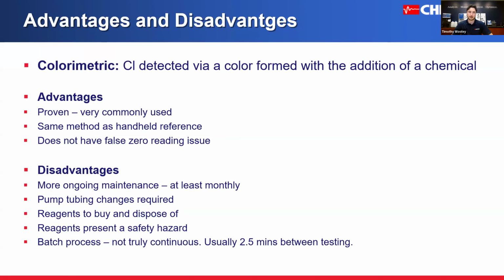And these typically do not have the false zero reading issue. So these are better fit for dechlorination applications or times where there might not always be chlorine in the water. A few disadvantages, we would say, of this type of technology is that they do have more maintenance. So typically you would need to replace these reagents monthly. You purchase and replace them. These reagents do expire, so they cannot be stored forever.